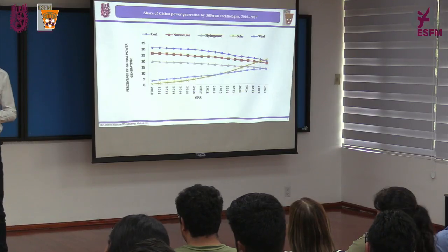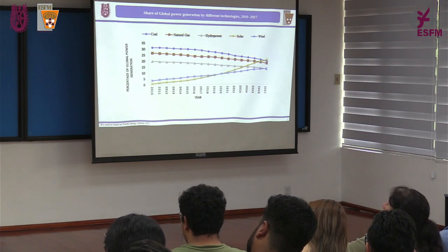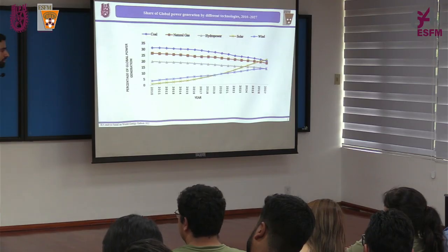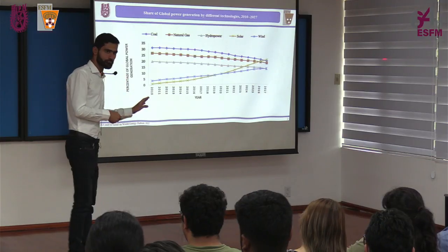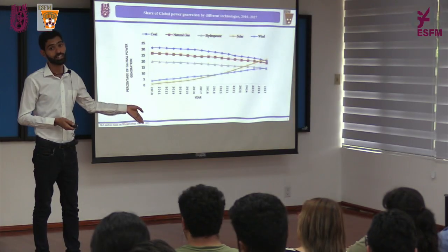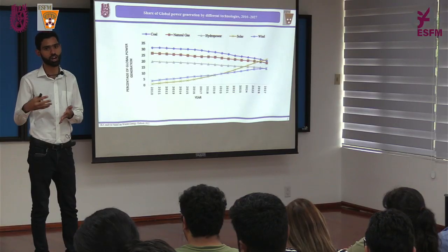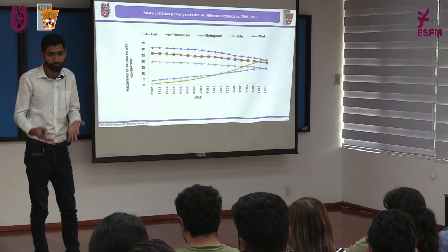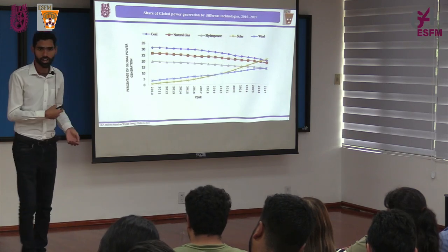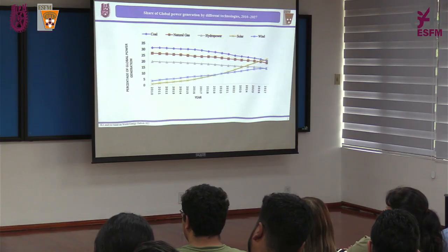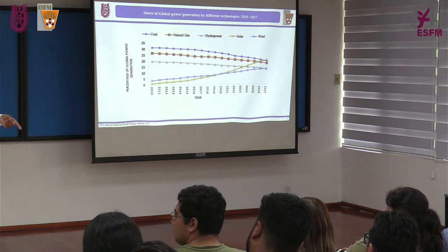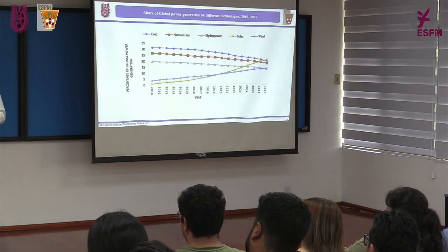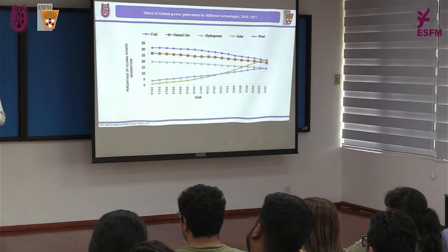The other part of your question is, can we meet the efficiency and the output of nuclear energy with solar cells? With the future projection, if we depend upon this kind of technology, we will have that much output from the devices. The latest devices published in new research have efficiency around 25%, 30%. I have even gone through a multi-junction device that has efficiency around 47%. But the main problem is the complexity of the process. If we make the procedure better, we can commercialize it and compete with the other kinds of technologies. Yes, it has potential.